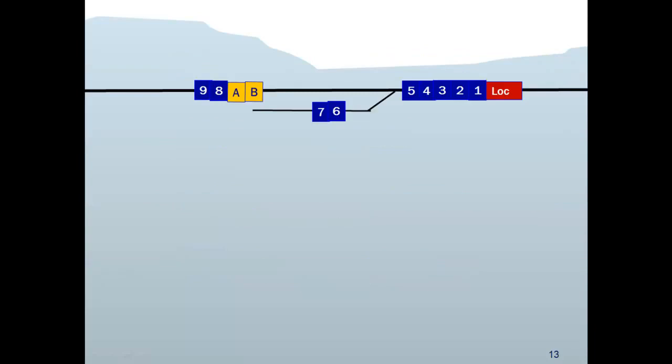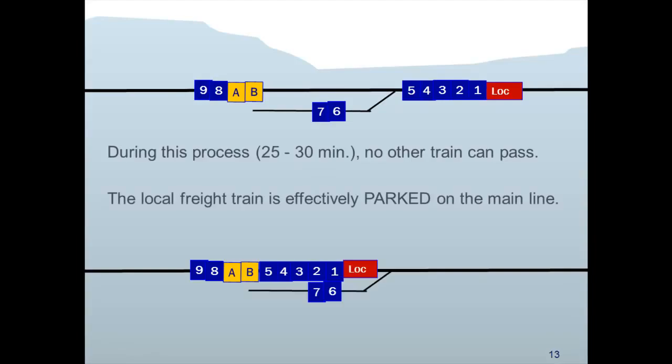The trainman then throws the switch so the train can go backwards to connect to cars A and B, which are also connected to 8 and 9. Finally, the train backs up to couple cars B and 5. The trainman then releases the handbrakes on A, B, 8, and 9 and connects the air brakes and tests them. The trainman can finally move the train ahead on the main line.